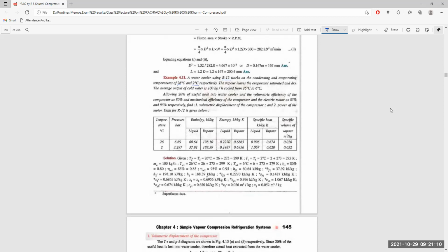So volumetric efficiency means how much of the total volume of the refrigerant is compressed. Compression is supposed to be 100% efficient. But as it is told, 80% only means it can compress 80% of this full volume of the refrigerant, because the remaining 20% may be wasted through leakage in between the walls of the compression cylinder or some other reason.